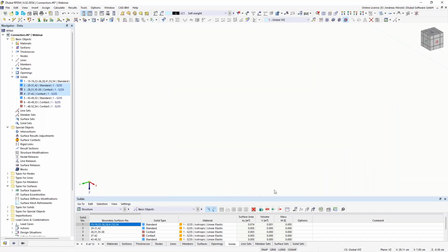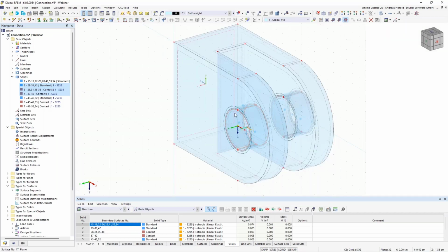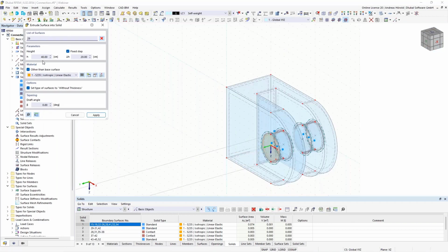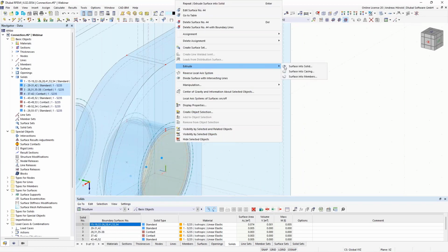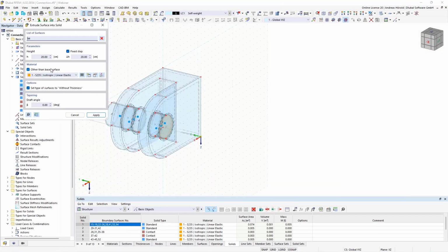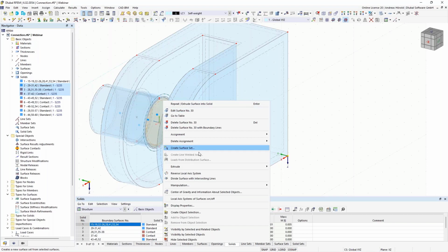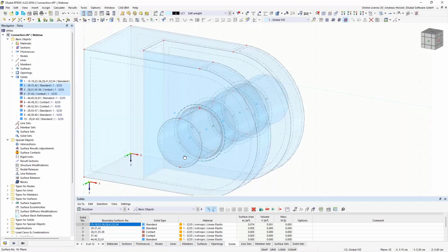So, and in the next step, I have to fill out the space and the overhang. I enlarge the bolt here. So with the extrude function, 3 centimeters, S255. Okay, same on the other side. That goes quite quickly. So -3. Okay. And the space here, also -3. Okay. So the model is complete.